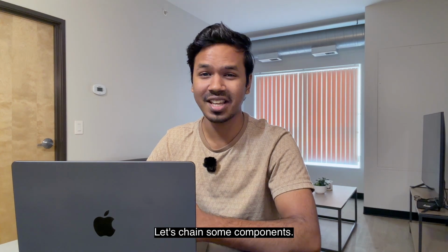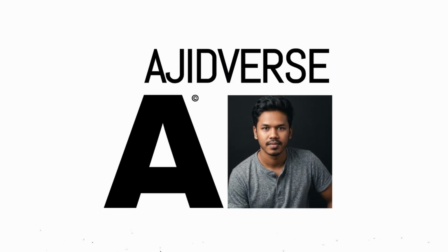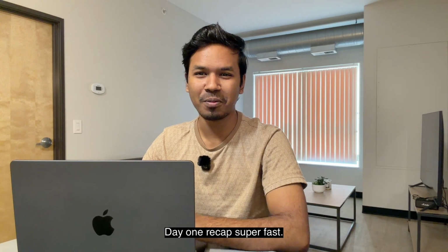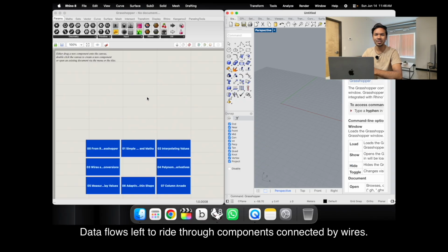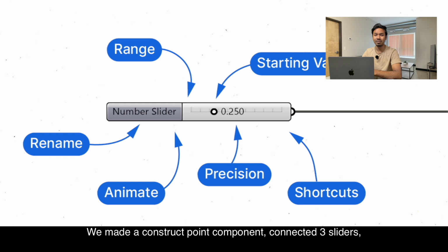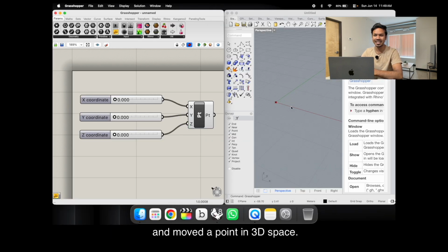Day 2. Let's change some components. Day 1 recap super fast. We learned that Grasshopper is a factory. Data flows left to right through components connected by wires. We made a construct point component, connected 3 sliders, and moved a point in 3D space.